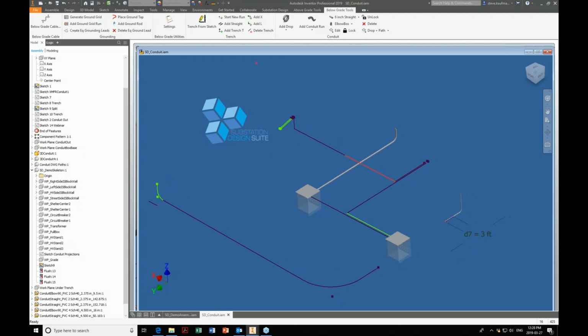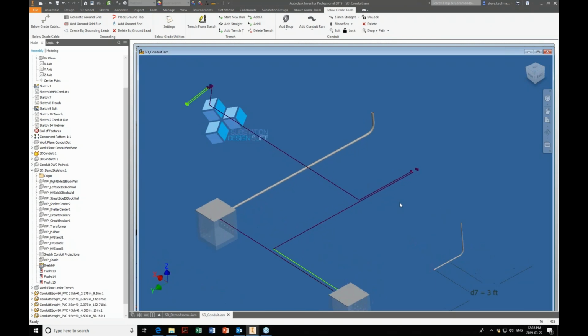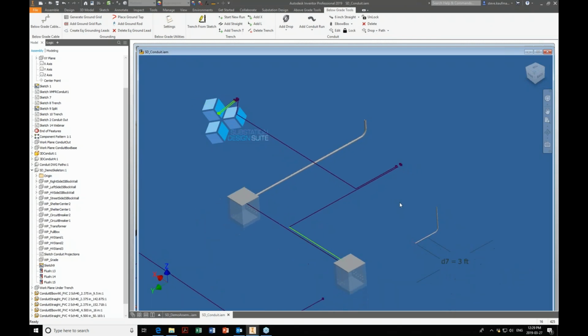So if you have the XY plane as your top of concrete, that's your reference plane. It doesn't have to be top of concrete, whatever you choose to be your reference point. So if you have a reference point from your civil guys, they say this is a reference point, like for the vertical elevation, you can create everything from that reference point. It varies on how you select your reference point, but you should try and be consistent with all your models.